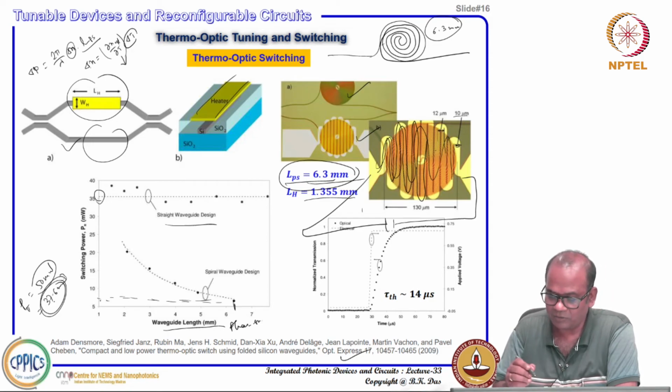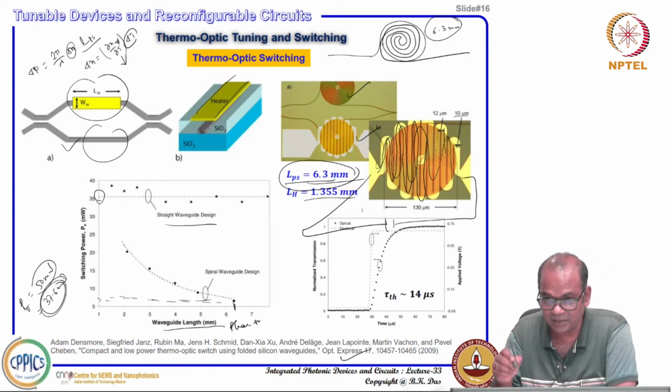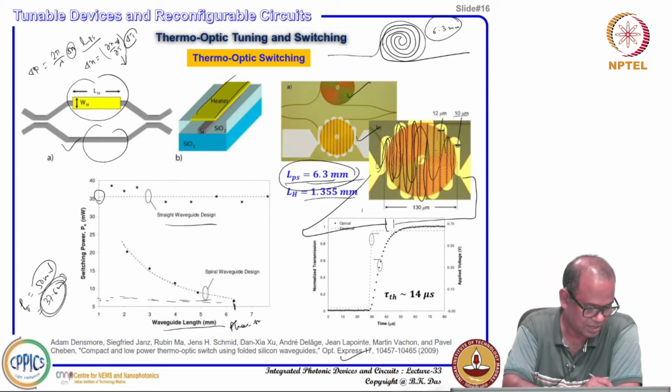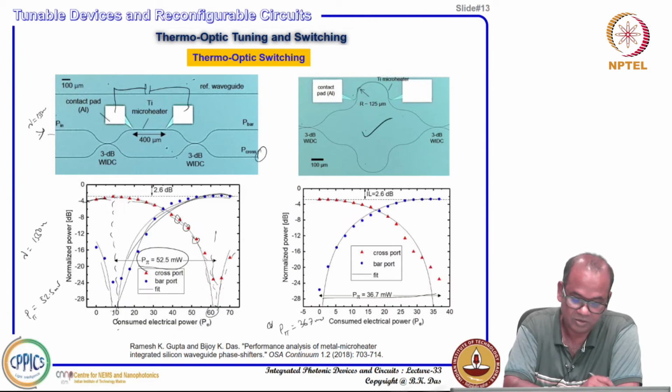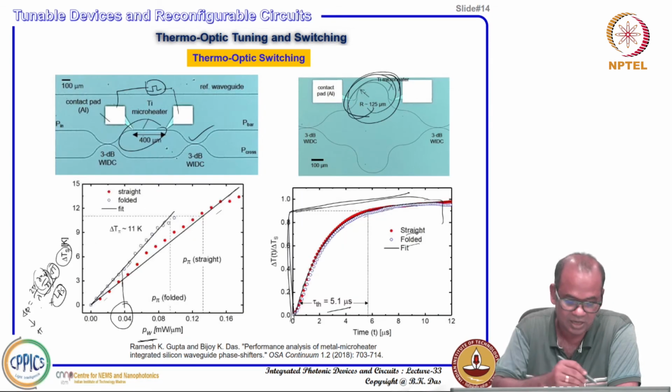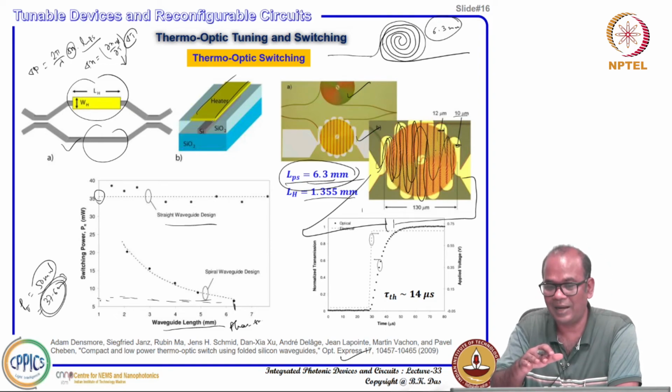Okay. But one thing is that this is a type 2 heater, just directly on the top of the oxide, not direct heating like we explained earlier, where this micro heater is in the slab region. There, the heater was integrated directly on the slab region, but in this example the heater is just on the top of your waveguide, above a certain thickness of cladding oxide layer.